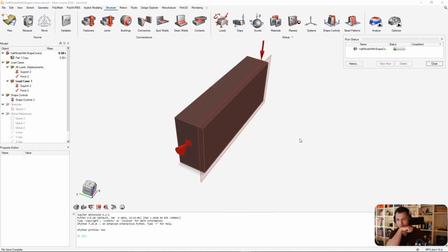Yeah, it's interesting. Because shape control, just think about what a shape control would do if you would be a guy who likes to program those things. A shape control, you would force the density of the topology optimization. You would force it to be symmetric. That's what shape control sounds to me. But if you have a shape boundary or shape plane, shape control plane at the boundary of your design domain, you don't have matching partners, you know?